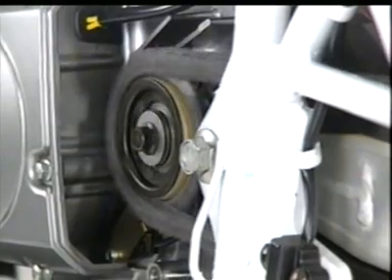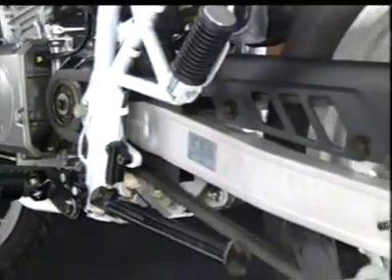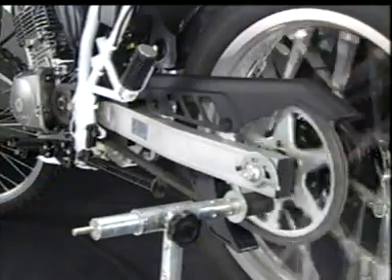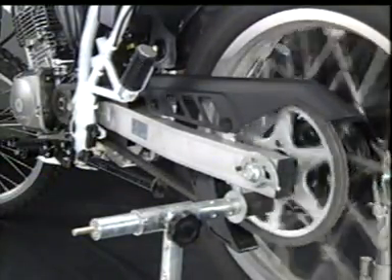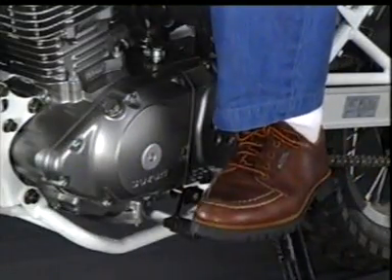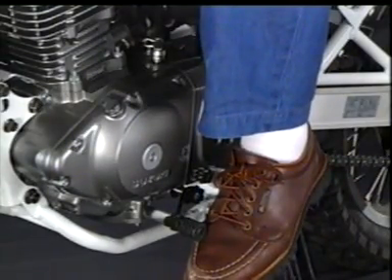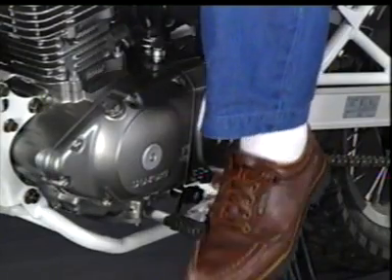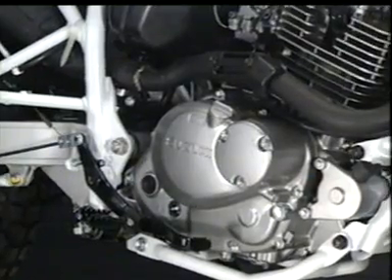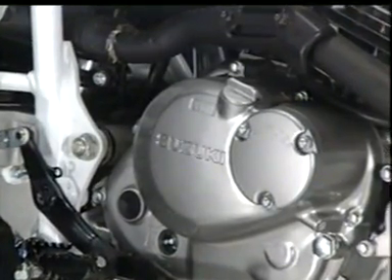In order for a motorcycle to start up smoothly, the power must be conveyed to the wheels gradually, instead of all at once. And once this power has been conveyed, it must drive the wheels smoothly and continuously without letting them slip. Also, when the transmission changes gears, it is difficult to shift smoothly from one gear to another unless we temporarily cut off this flow of power from the engine. The clutch is what enables this flow of power from the engine to be conveyed or cut off as necessary.